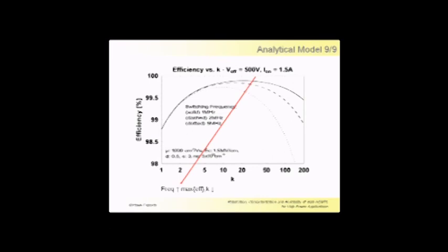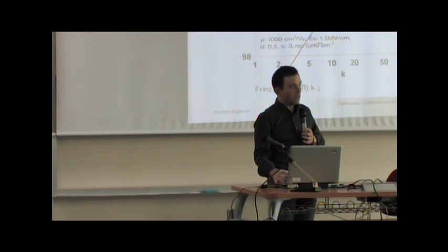This is the last simulated scenario. Changing the switching frequency, we can clearly see that the efficiency goes down as we found in the equation of the switching losses. And here we have switching frequencies from 1 megahertz to 5 megahertz. Of course, increasing the frequency, our efficiency is going down, but we can compensate this increase in losses by reducing the DC components in our switching system.